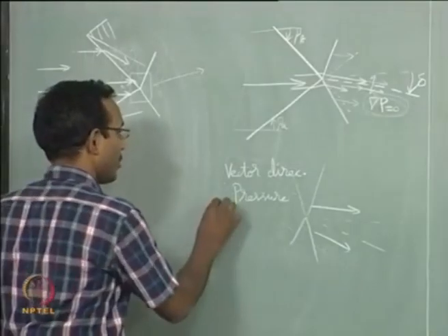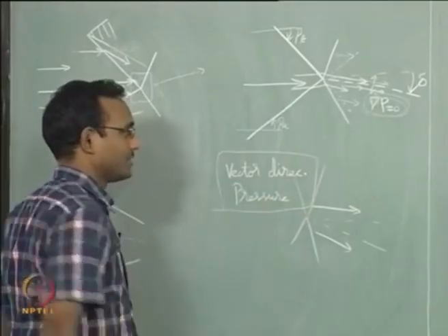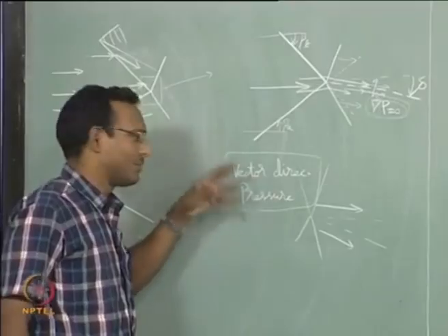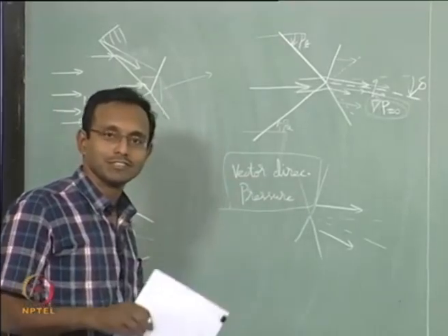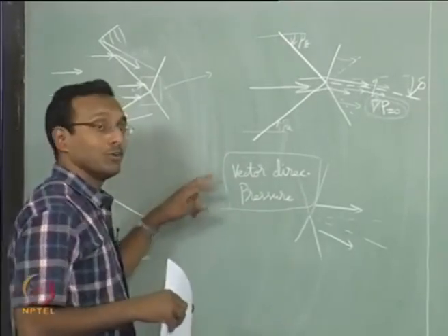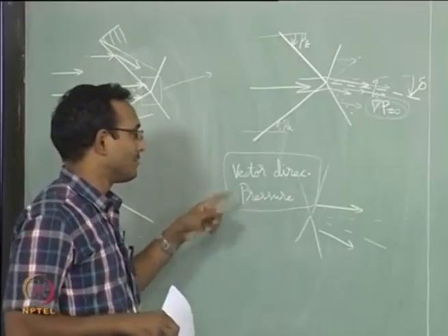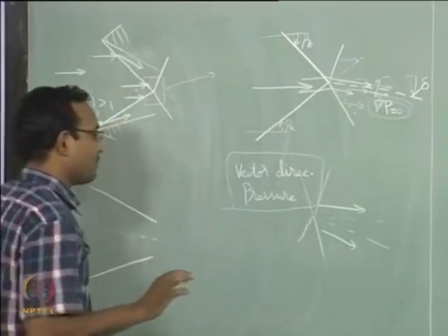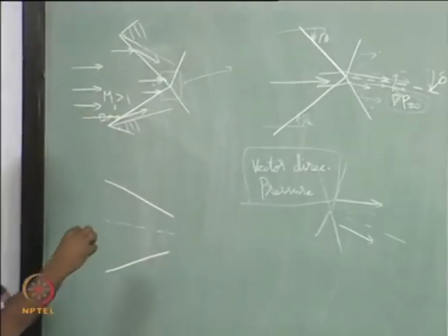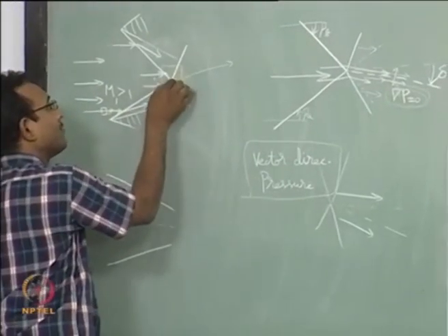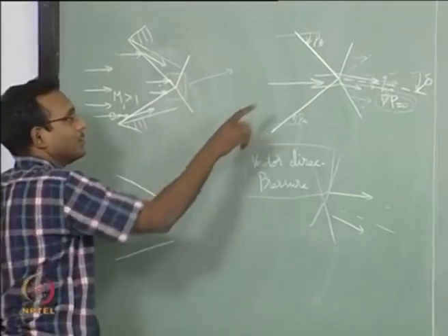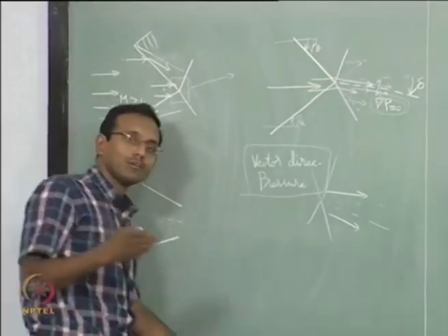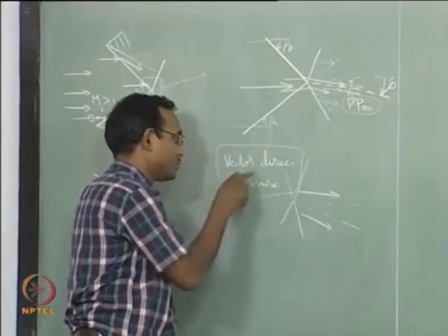These are predominantly applied as boundary conditions in your flow. We do not care about vector magnitude really. Whatever the velocity, I just have to make sure that the direction is fixed. Magnitude will affect the energy in the flow, but we are just talking about this currently. So if I want to solve this problem to find the angle of deflection this way for the new shocks after reflection, now I have to go and talk about satisfying these two conditions.